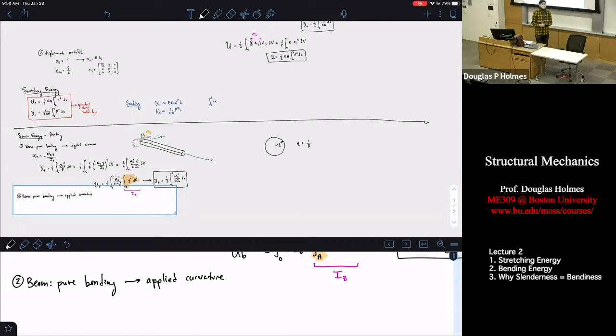So you might not remember this as well. You use this in mechanics of materials when you're doing the derivation of the shape of a bent beam, which is usually called the equation of the elastic curve. Basically, I've got my beam, it's simply supported, and I'm applying some load to it. How do I plot what the shape of this thing is? You might remember having a fourth derivative equation that you have to integrate 4 times and apply boundary conditions to find what the shape of this thing is. Maybe not.